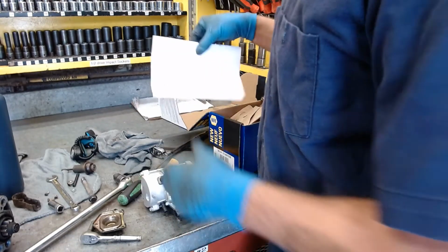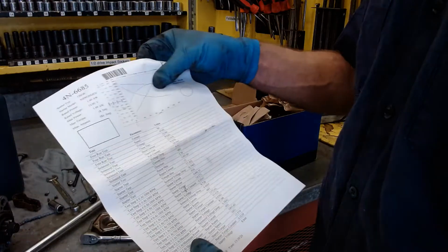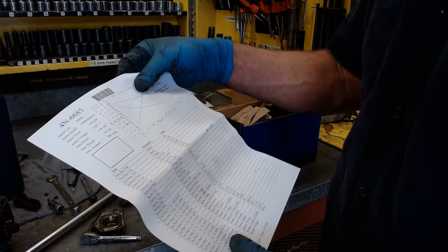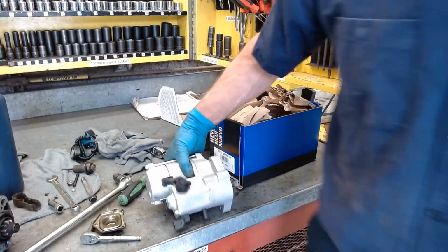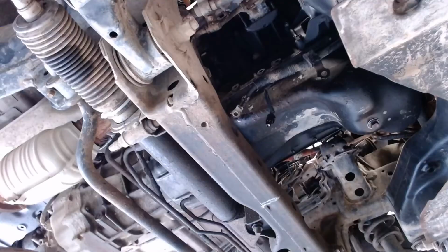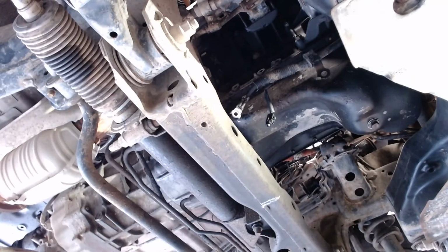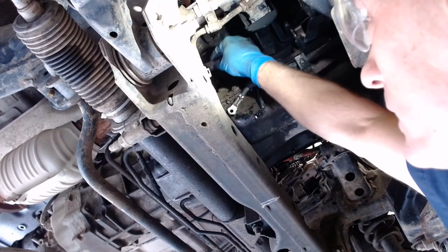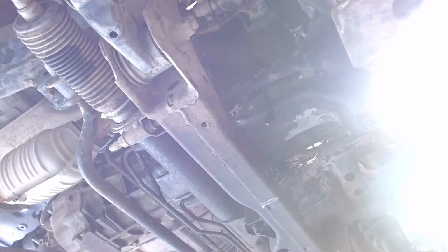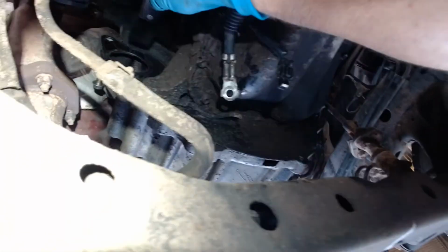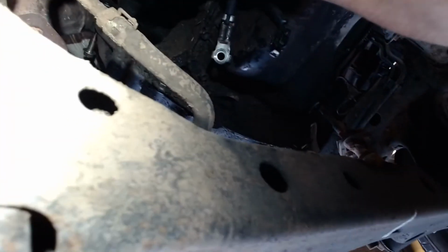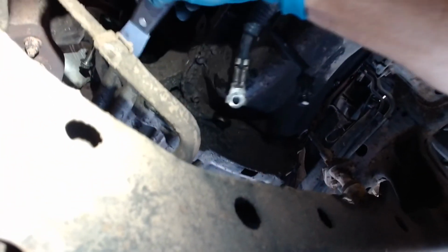So they give a whole spec sheet with this new starter. It tells all kinds of performance measures, etc. So let's put this guy back up in there without dropping it. Okay, what I'm going to do is I took this gasket scraper and went up here and cleaned this off, and I'm going to hold this up so you can see a little better. So I went up and scraped this off right here. So there's no grease or anything that's going to keep the starter from sitting flush.